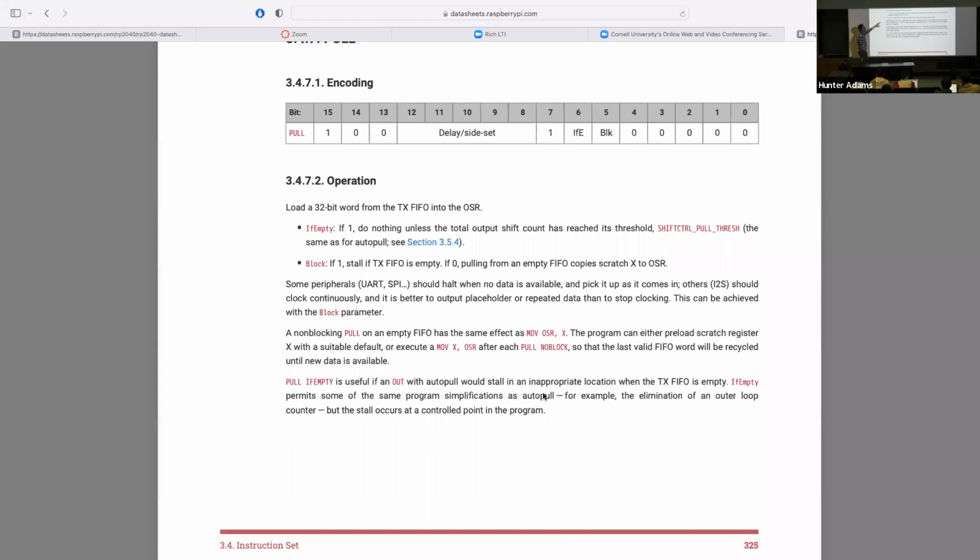The TX FIFO can signal when it's empty to a DMA channel so that as soon as we have moved all the data out of that TX FIFO into the output shift register, maybe for ultimately being put out to the pins or something like that, we'll look at some point this week at a PIO-based implementation of a stepper motor driver, and that's approximately how that works. We can have the DMA channel automatically start its next transaction immediately when the TX FIFO empties, so that you're pulling data in from the TX FIFO. As soon as it empties, the DMA channel pops more data in there.